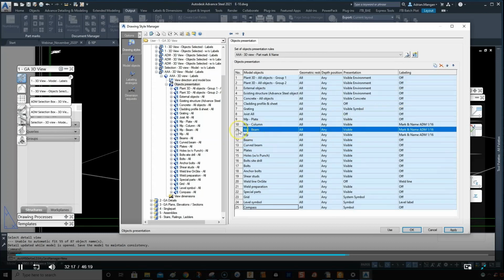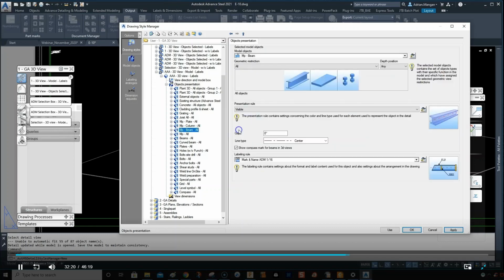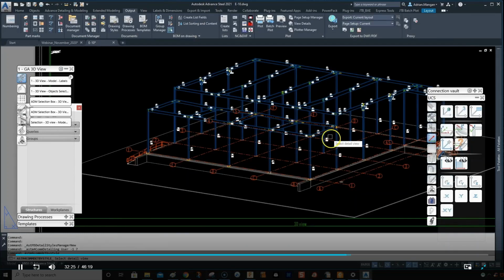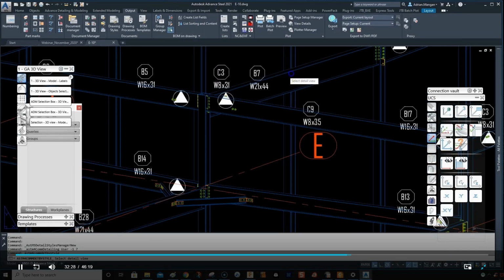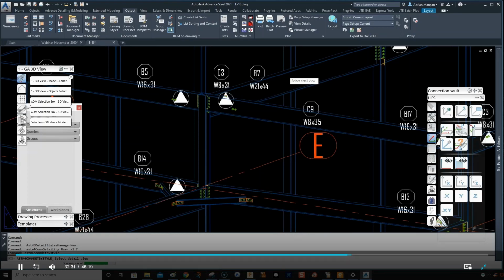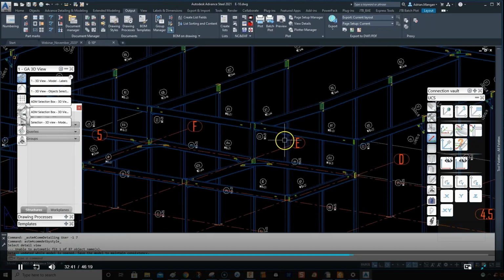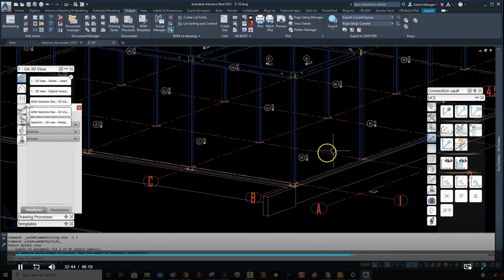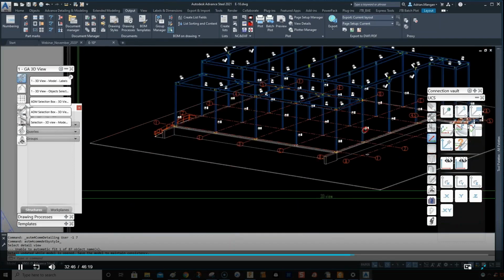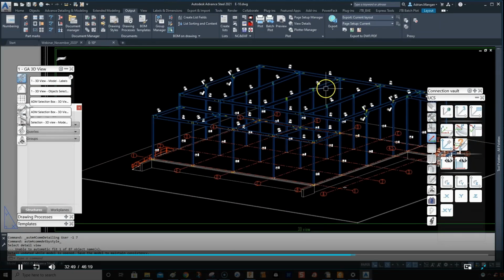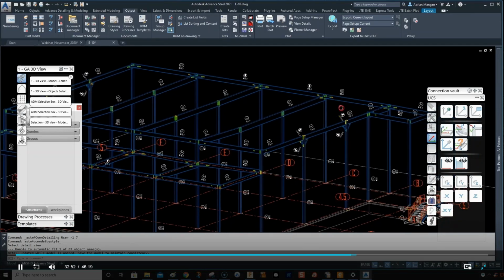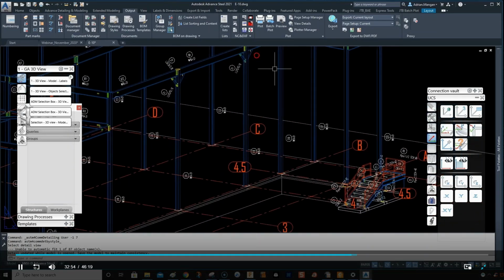And then what we want to do is double click on this. We want to turn off the compass marks, apply, use, and these compass marks will disappear. And then we can just have it where the numbers are on the correct end of the beam for erection. We don't need to have this mark on the drawing. So you can see then that my labels for my columns have gone the right direction again, which is the way I want them. And there you kind of have something close to what you want out of the box.